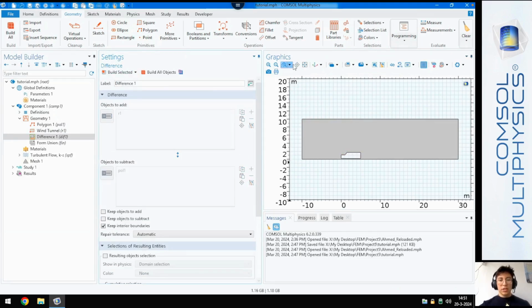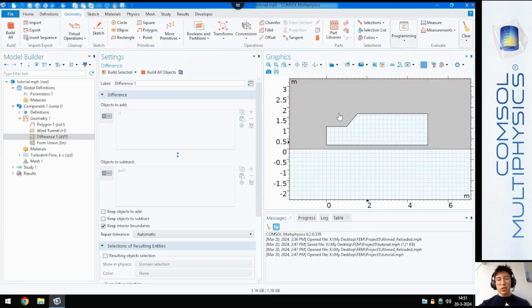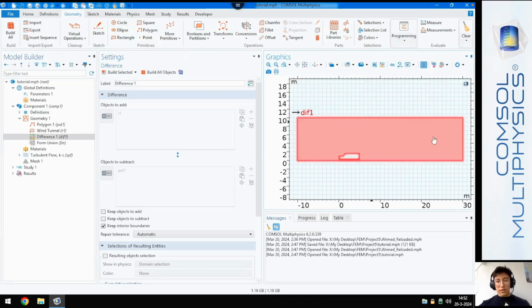And as you can see, this works quite nicely, because now what we're going to do is define the fluid inside of this entire container, and then we're just going to have a cutout here. This is computationally a lot more efficient and also gives us more control over the mesh, because we can define it using box refinements, but also, as we shall see later, it's just a much cleaner way of doing it. You also don't need any extra materials. You can just work with the air itself, and then you don't have any weird things happening with that.